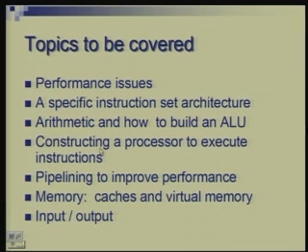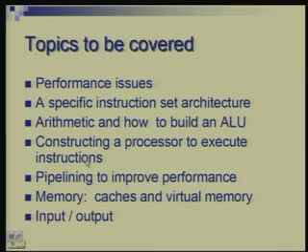So, ALU is just one part of the processor. You have to put register files, you have to put buses, you have to put a program counter, and you have to put a controller to make the data flow into various components properly. So, next we will be dealing with the design, the flow of data, the data path, and the controller.